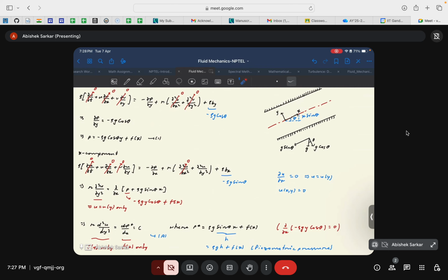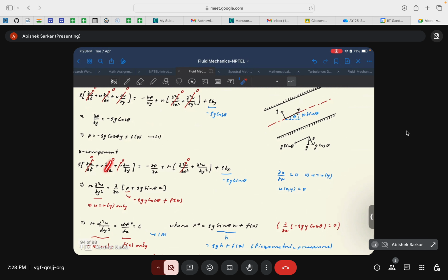So now you can see that because we inherently considered that the flow is fully developed, it essentially removed the non-linearity from the equation that was there in the left hand side, in the convective acceleration terms. And that is the pattern that you will see. The assumption that we make, one way or another, removes the non-linearity that helps us to obtain the exact solution.